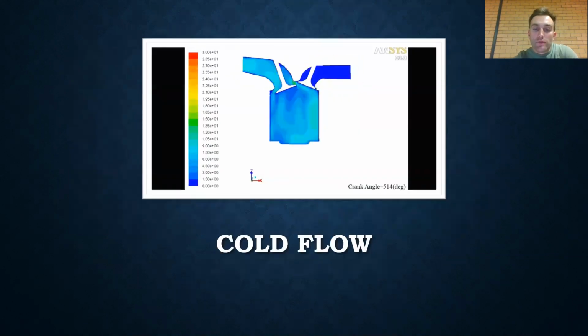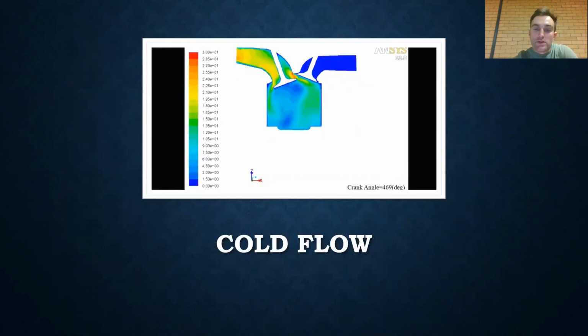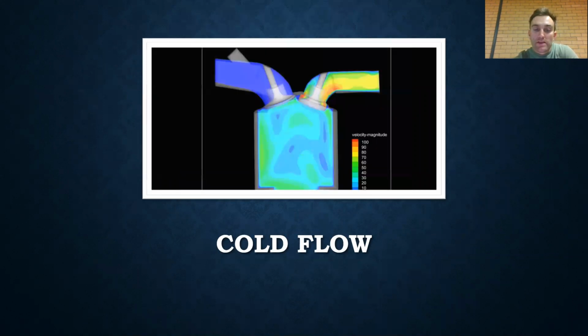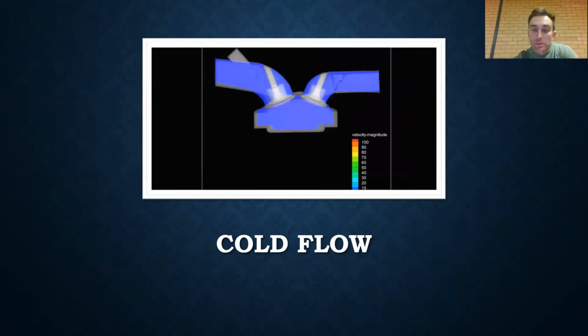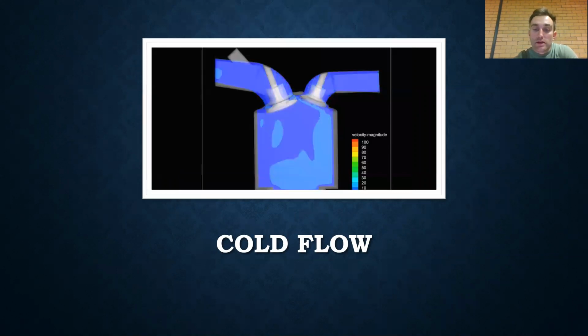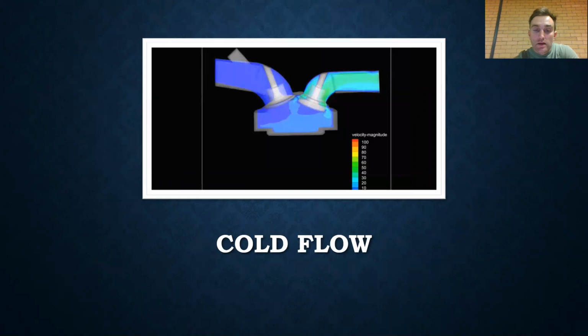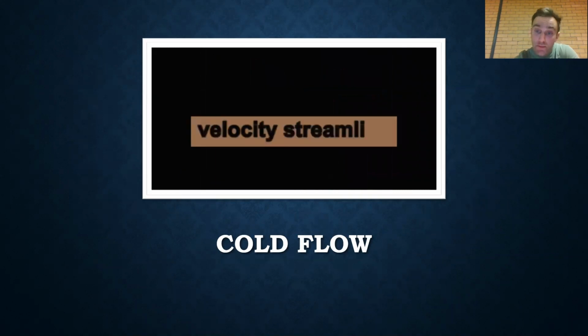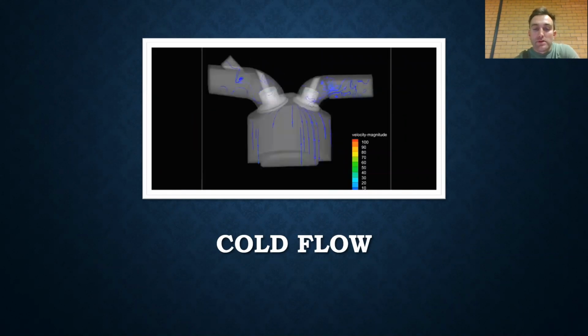The second is cold flow analysis, which allows you to simulate a full engine cycle without the effects of combustion. This allows you to investigate a complete airflow through the engine at set engine speeds. It allows you to investigate the level of turbulence at any points of interest inside the engine cylinder at different points of crank rotation, as can be seen here.